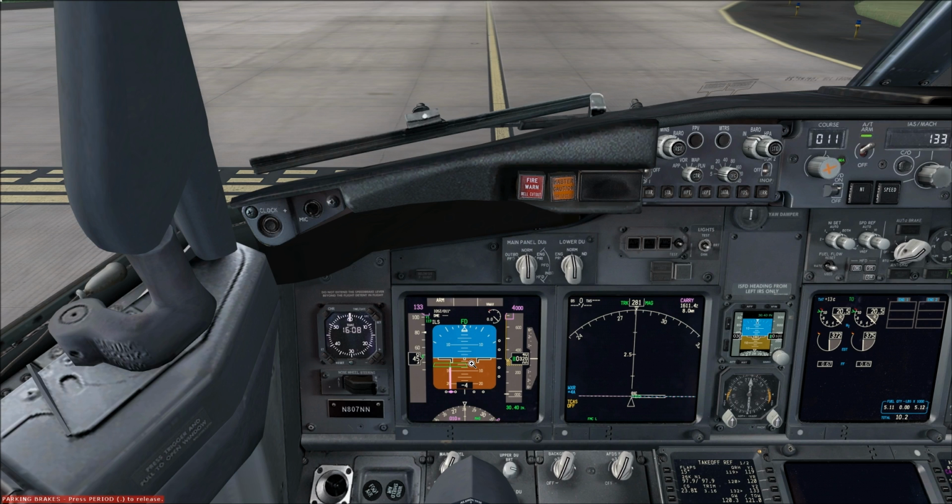Now the windshear escape maneuver, if you want to do it manually: you disconnect the autopilot, press either toggle switch, aggressively apply maximum thrust, disconnect the auto throttle. Simultaneously roll wings level to get maximum lift, and rotate towards an initial pitch attitude of 15 degrees. Retract the speed brakes, follow the flight director TOGA guidance if it's available.